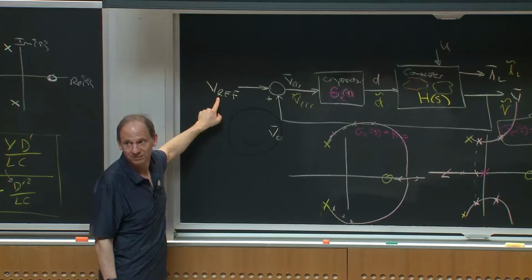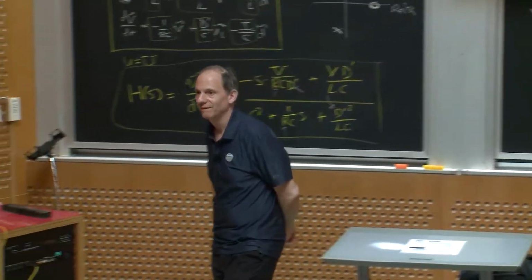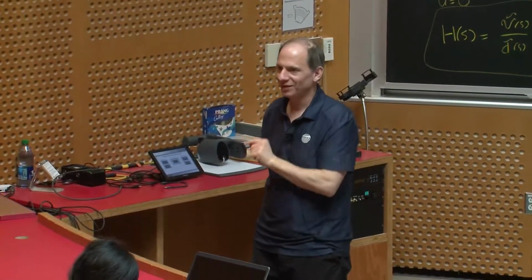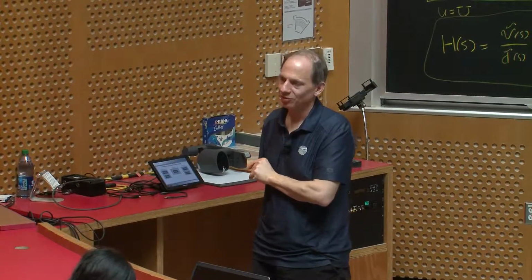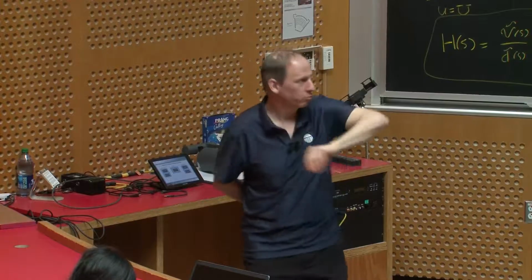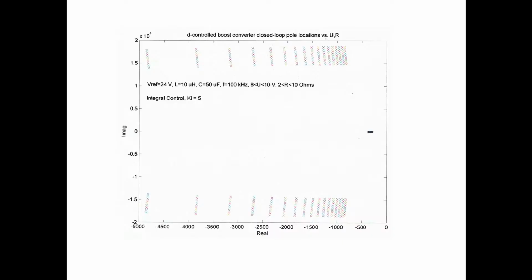Well, yeah, I guess I'm asking because the phase margin that's high is pretty heavily damped. Like 90 degrees is pretty heavily damped. Right, but the only thing that's telling you is what the dominant pole is doing. It is very damped, right? The majority of the transition will reflect that dominant pole. So the reason this looks damped is because it's dominated by this guy down here.